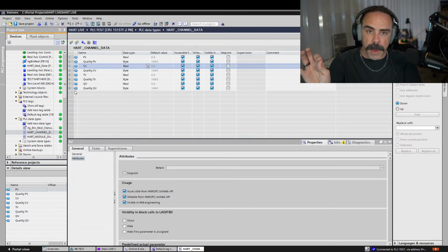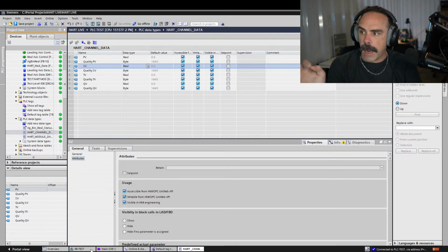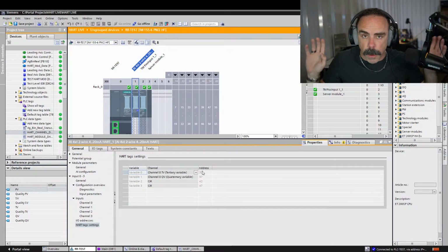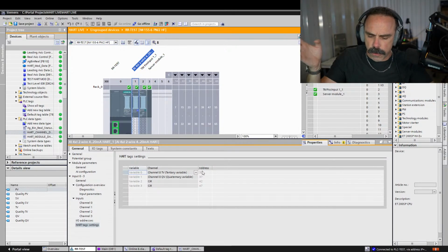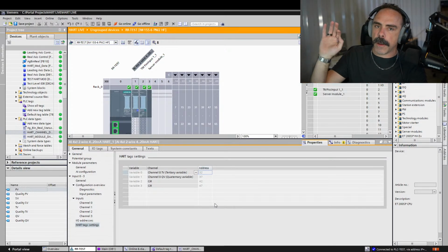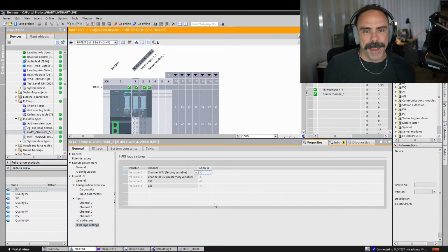So you can create a PLC data type for this, but you have to point it individually at each address. And maybe that's the dumb American part that, oh yes, you could just do this. But yeah. So the 32, 37, 42, that's the easy way. You can just bring those into your tag table, use them real simple. You can address them directly from an HMI using direct memory addressing, all of that, perfectly fine. It works.